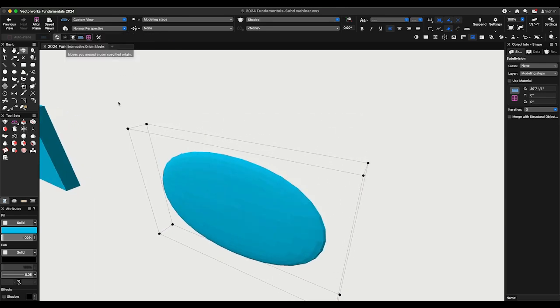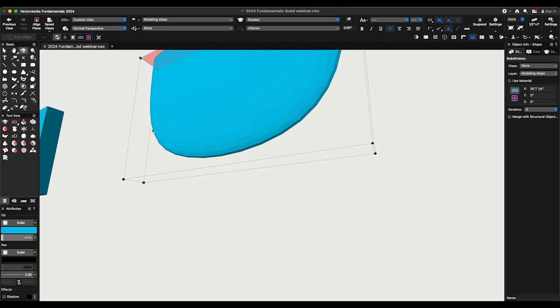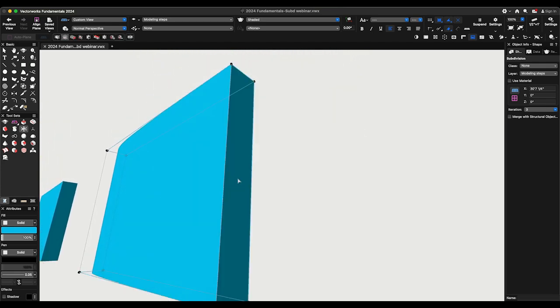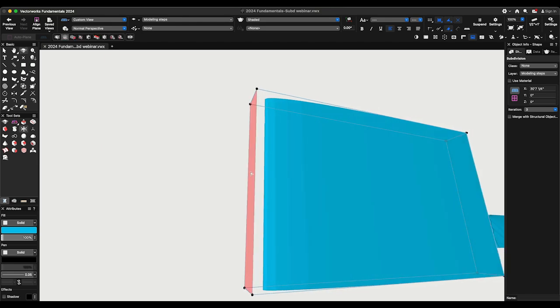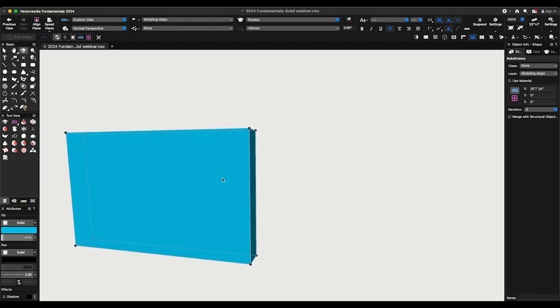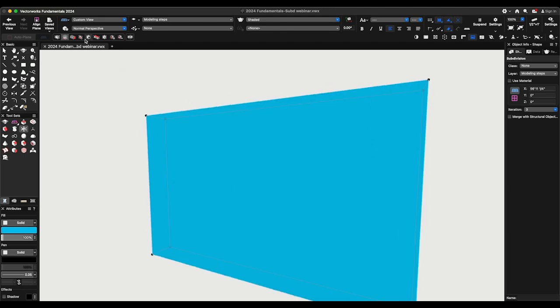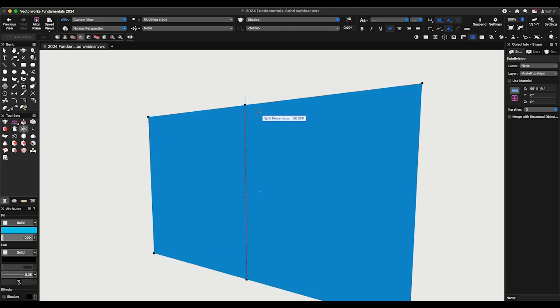I'll use a crease mode, and I'll click on these faces to make them flat. One here, another one here, and here. For my next step, I'll use the split mode. I'll start touching this edge and type 50 for the percentage. I can also find the middle snap points to divide each face in half, a few vertically and just a few times horizontally.